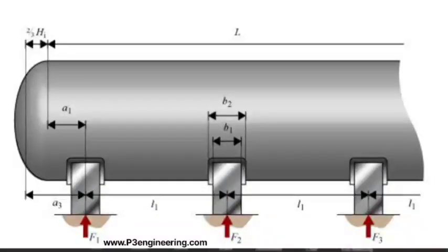Yes, that is what we did. We divided the tangent-to-tangent length with the number of saddles that we were using, 3 saddles in our case. So we placed the third saddle at a distance of 1/3 from the other two. But the thing is that there was no proper way to verify that the third saddle was taking the effect that it should take. That is the problem.